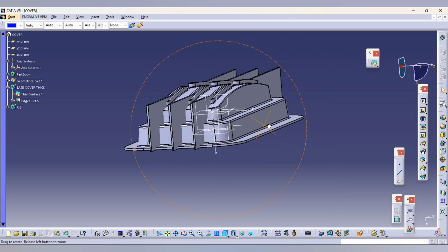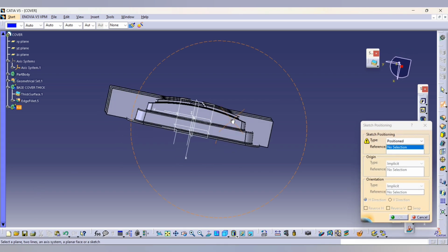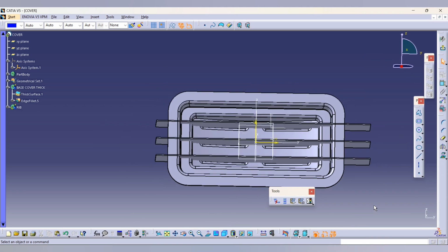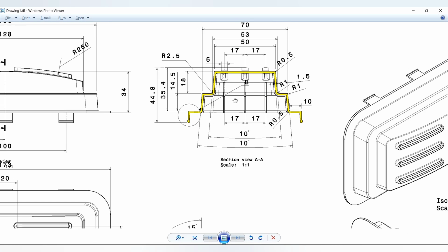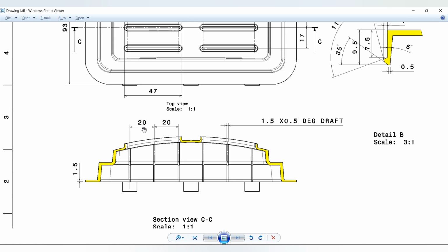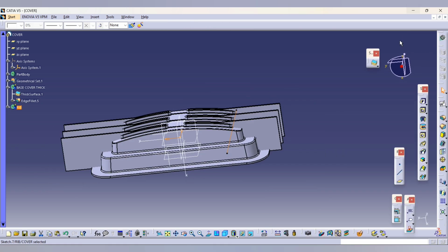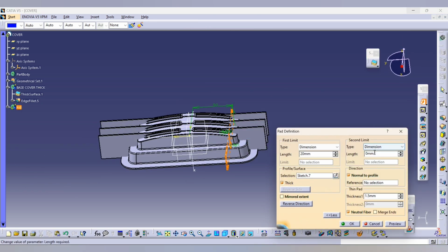So we'll pattern the three lines or three pads. Then we'll do the next rib. So those horizontal ribs are completed. We'll see the vertical. The dimension is, you can see, 20, 20, and from the middle 10, so it's 50. As usual, we'll do the pad thickness, everything.